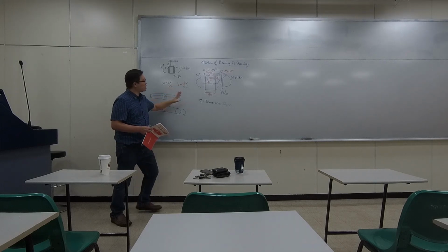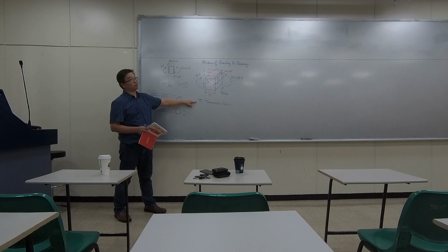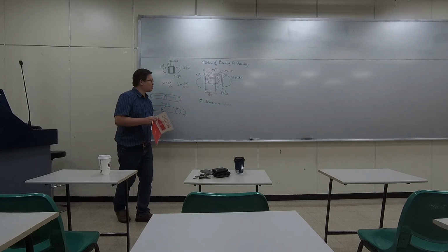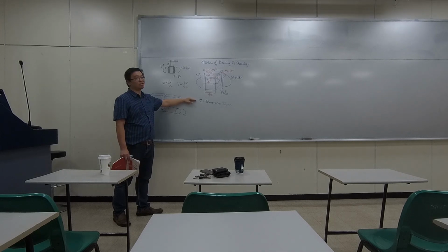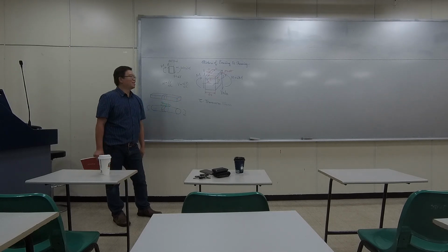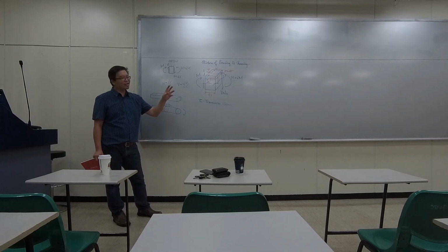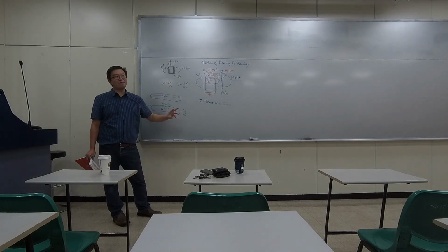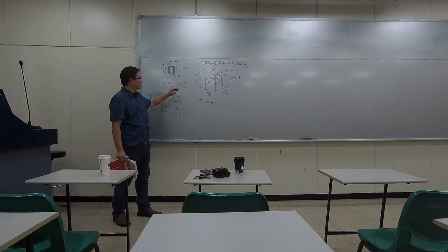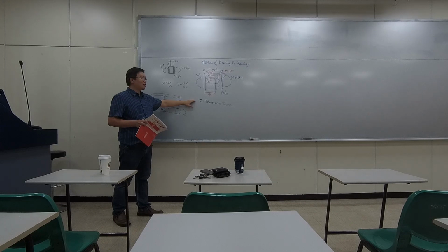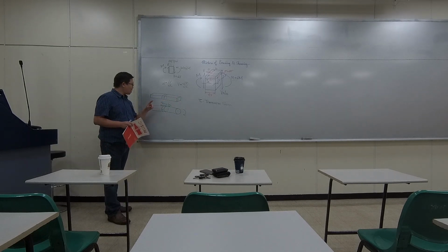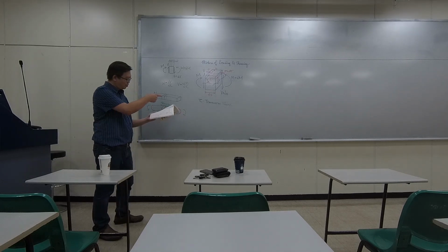If this is 0, later on I will let you know, this becomes 0. So if we have a pure bending problem, we also don't need to talk about transverse shear. However, in the homework and the exam, both problems were not pure bending. So theoretically, we need to talk about it. However, if we are only talking about the very top point, then it's not an issue. Okay, so let's continue on this part.